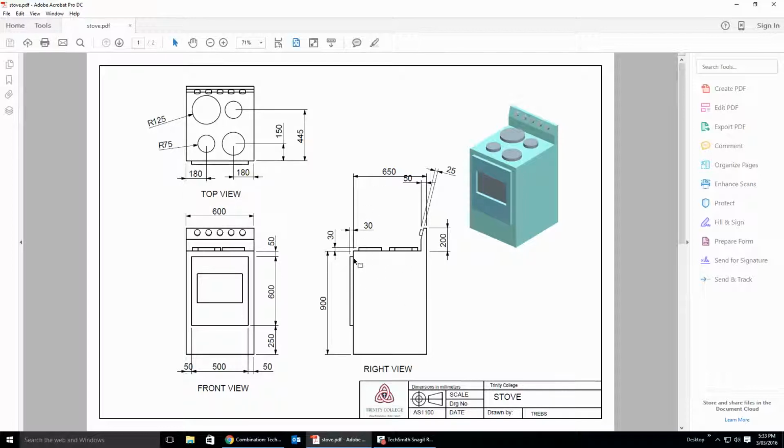Once we're finished on that, we won't draw any of these side objects here, but we will use some of the measurements, like the extrude here is 30, which represents the oven front. We'll then move on to drawing this part here with our dials across this face. You'll also notice we're not showing any widths here, but we do know that the total width here is 600 with 5 dials. So we'll try and make an approximation for those dials to sit across. We could be quite specific, and we'll show you how to position those across there.